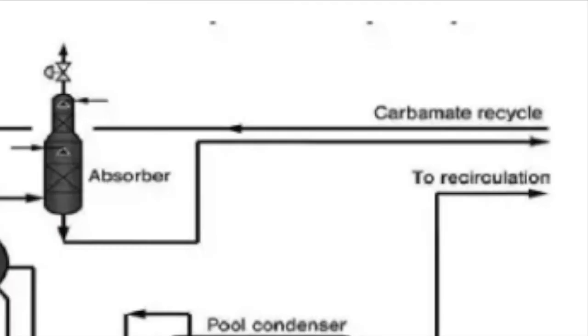The ammonia and carbon dioxide present in the discharged urea solution from the stripper are recovered in the low-pressure recirculation stage. The urea solution that leaves the recirculation section is concentrated further in the evaporation section from 74 to 98% by weight. Evaporation is done in a vacuum to minimize biuret formation.